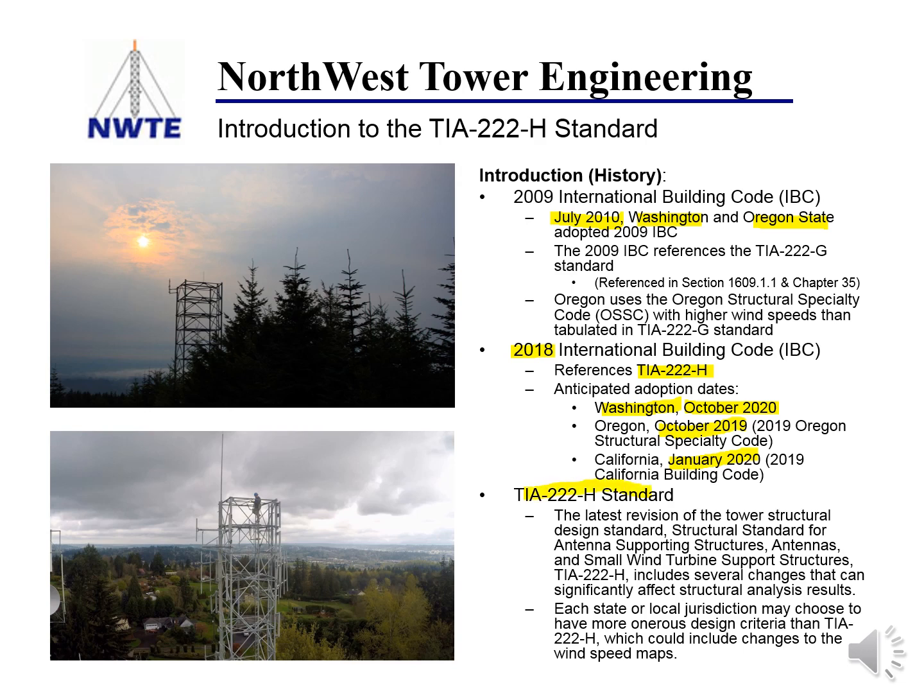So the H standard includes several changes that can have a significant impact on the structural analysis we're doing on towers, particularly existing structures. Each state or local jurisdiction may choose to have more onerous design criteria than that referenced in the H standard. In particular, they may make changes to the wind speed maps.